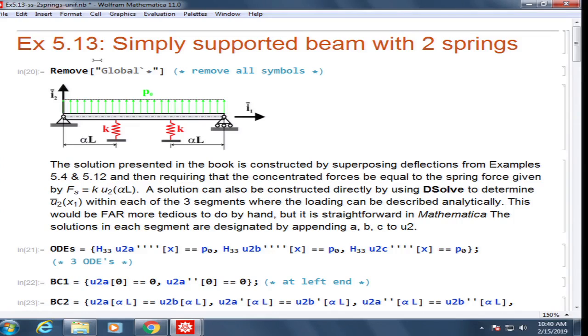So I'll just use u2 double prime. There is no restriction on moments. I do not have a rotational spring, so it should be continuous, right? So I don't have enough equations. I need 4 equations. I got that in the previous problem by saying my displacement is 0. So I had 2 equations there, but not in this problem. So we need one more equation on shear force.